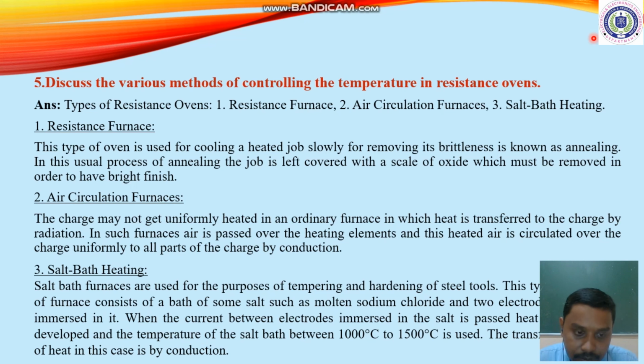When current passes through the electrodes immersed in the salt, heat is developed, and the temperature of the salt bath is about 1000 degrees Celsius to 1500 degrees Celsius. The heat transfer here is by the conduction method.